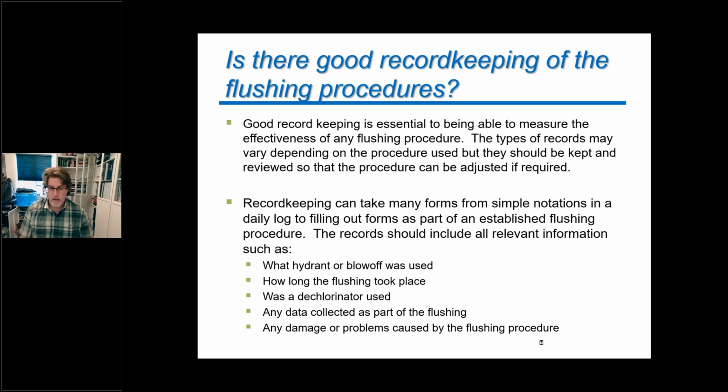Also, the data that you collect while you are doing this. This was the chlorine residual when I started. This was the turbidity when I started. This was the turbidity, chlorine, pH when I finished. Whatever it is that you are measuring, we need to make good records of that.